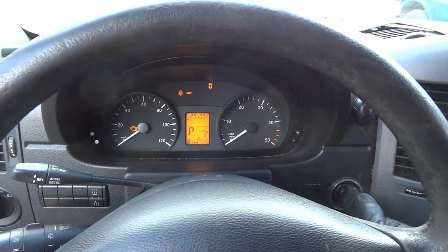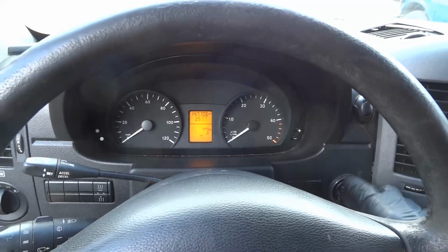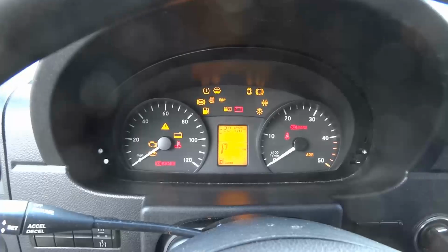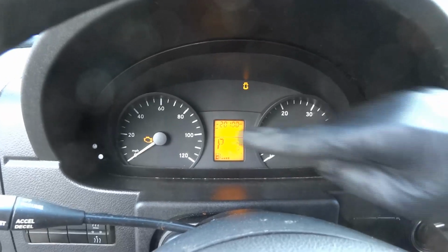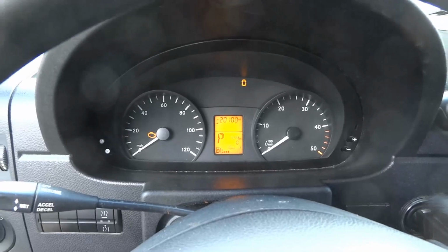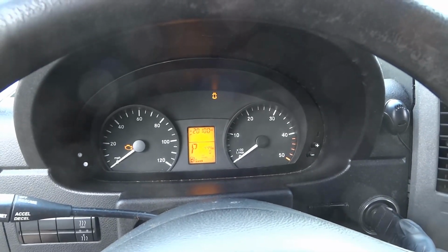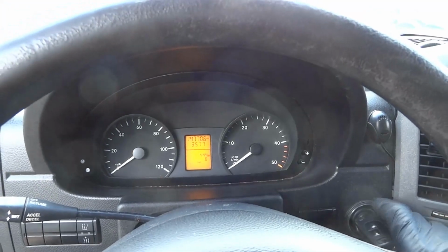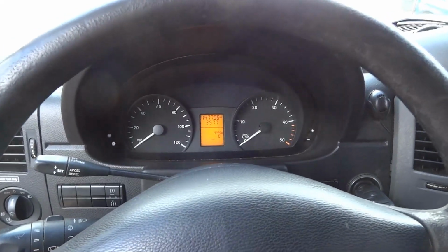I hope you guys can hear the engine cranking. The engine cranks, but it doesn't start, okay? So now with the key on, as you can see, all the lights on the dash illuminate initially. The check engine light is on, which tells me that the computer is powered. So we're good there. So let's crank it one more time. As you can see, it cranks, but it doesn't start. So we have confirmed the complaint.